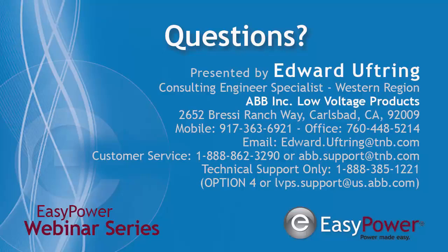Maximum current interrupting rating. So again, this is the most current that our device can stand to open and not cause any damage. So after we get above this maximum current rating, so if I have an 800 amp breaker in there, if I see 900 amps, that's above my maximum current rating. That means you can see damage in the breaker or it cannot function at all and you can have fusing of the contacts. My short circuit is 40 kA. Will it be okay? Yes, it will be okay to use a 42 kA rated breaker.